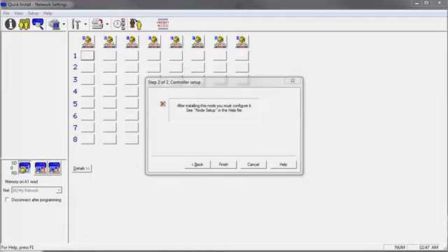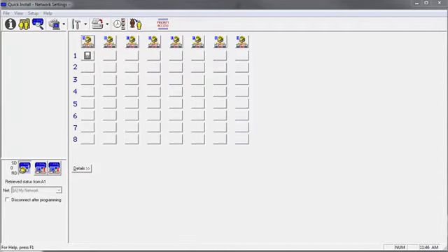On the last screen of the startup process, we must configure the panel or node. By configuring the node, we are telling the panel what it is wired to, a card reader or a keypad. Once we've installed the panel, select Finish. The node is now steady, as it is no longer flashing, and step 1 is complete.